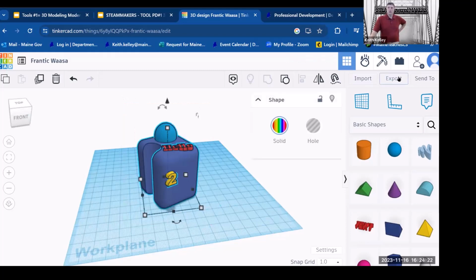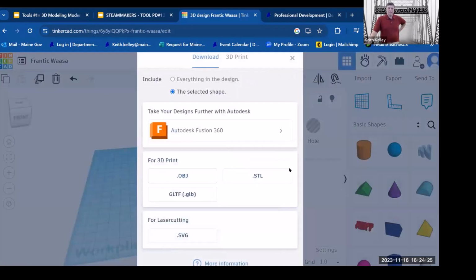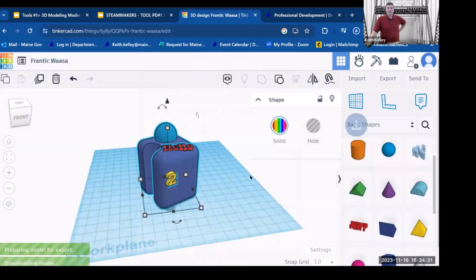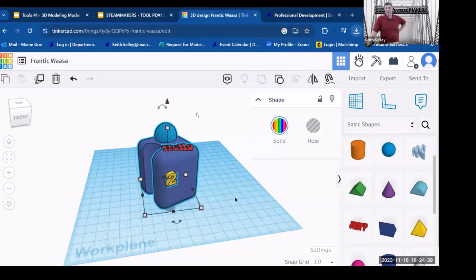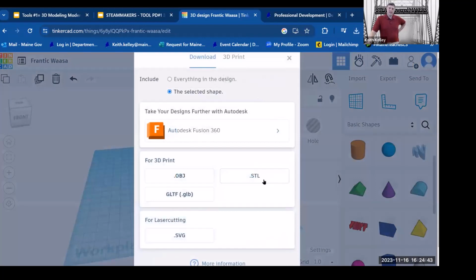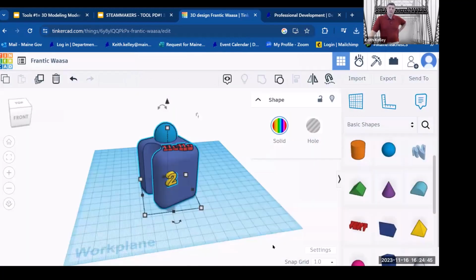They will export it and send it to me as an STL or an OBJ or so on. So I'm going to hit STL. I'm downloading a standard tessellation model is what it really calls. So I just download it. Now, Tinkercad will do weird names for the files because they have so many objects. They always have weird names. If you export STL, it will come like this.